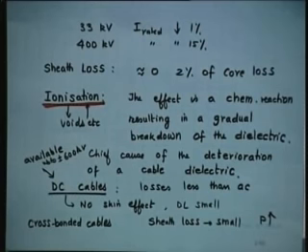Do not think that you have created void while manufacturing, and if it is in India, people are careless, maybe voids have been formed. But even if manufacturing is perfect, it is made in England or made in US, void can still be formed while in use because of contraction and expansion. Chief cause of deterioration of a cable is dielectric, and dielectric is a must.